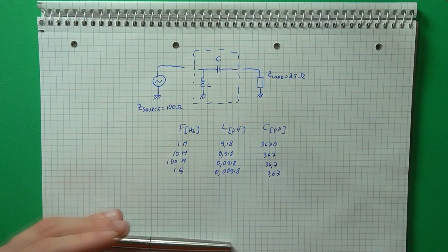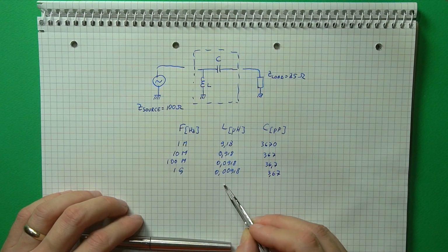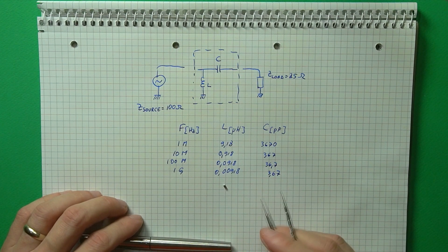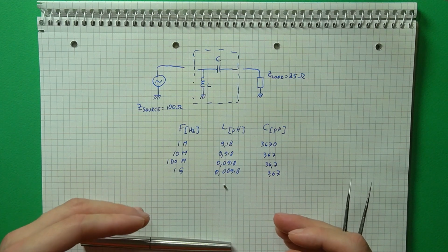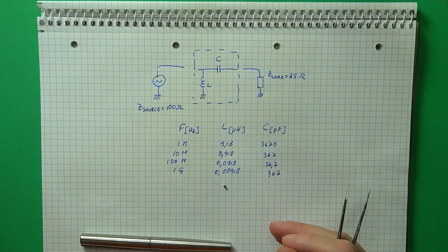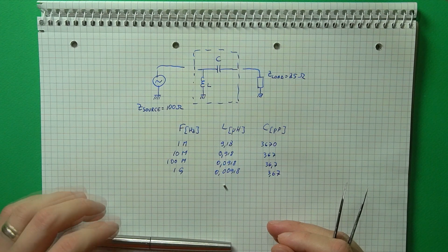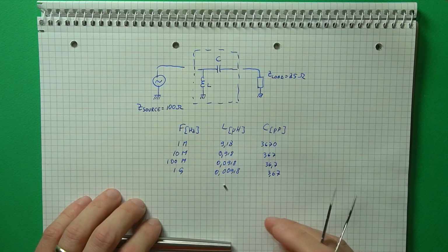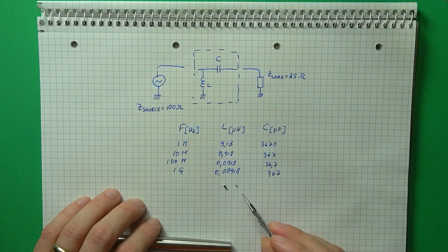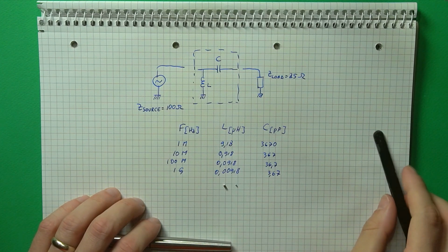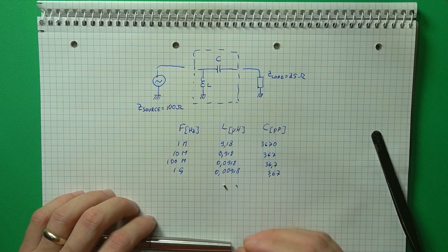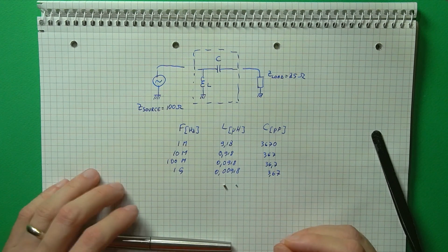Now, to give a bit of context on this, a 1206 ceramic capacitor by itself has about 670 picohenries of built-in series inductance just because of its size, and an 0603 RF inductor can have somewhere in the 0.1 to 0.5 picofarads of parallel capacitance.